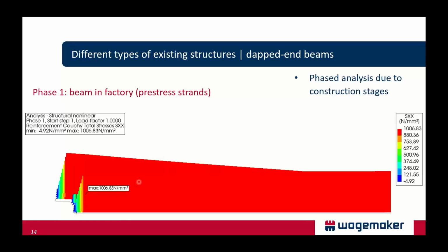So model validation is always an important part. So we started with checking whether the pre-stress loading was successfully adopted in the model. So as we expect from a prefabricated beam, the pre-stressing stress at the beam's head is 0, and it gradually develops over its anchorage length to the maximum. So this one looks okay.